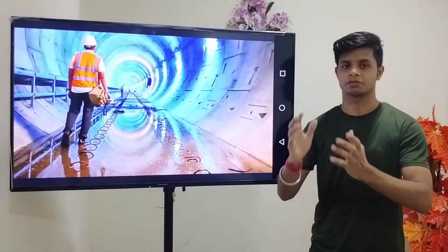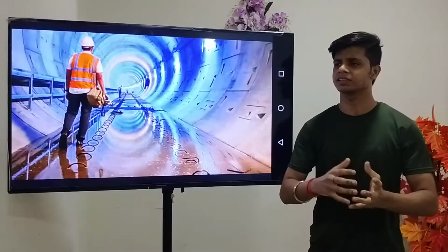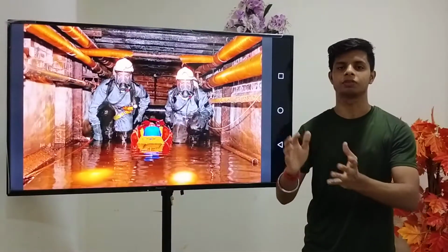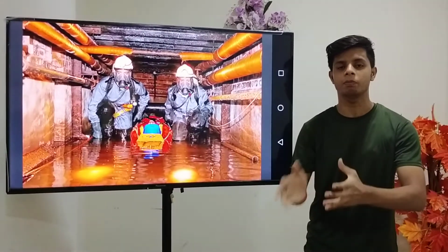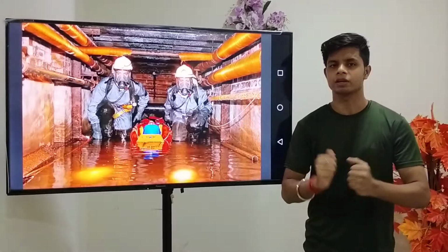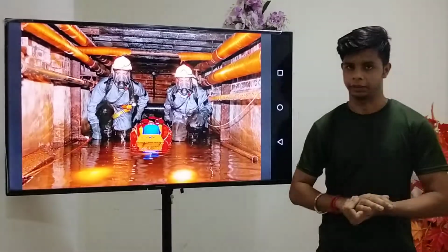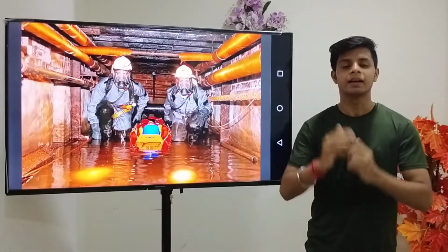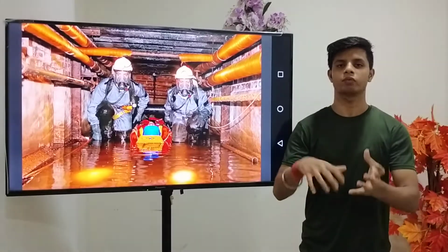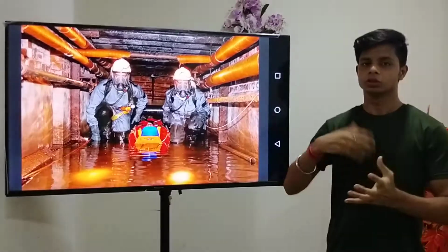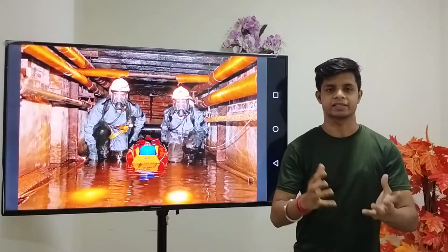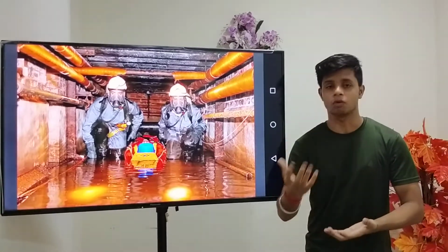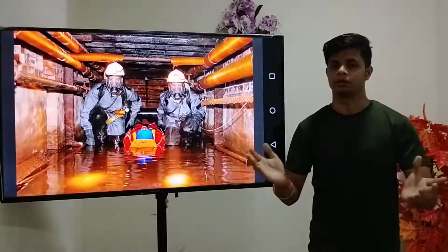Now, if we come to the hazards associated with that particular confined space, hazards are multiple, but they depend upon what you have previously stored in the confined space. For example, if you are working in an agro industry, where you have stored some sort of grains in a silo, what are the major hazards that will be present inside? These are dust explosion hazards, because in agro we have multiple dust explosions. If we come to the specific hazards, they include fire and explosion, afterwards engulfment, as well as the risk of release of potentially harmful gases, multiple. These are some examples.